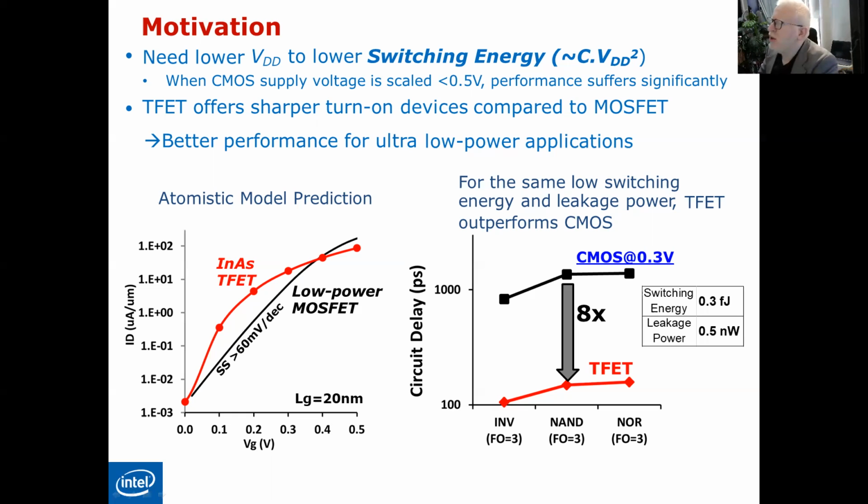So when I told you, for example, that in the past we were using a 60 micrometer technology, this 60 micrometer technology is simply the channel length. This was something like 10, 15 years ago. Now we are using up to 7 nanometer technology. What I mean by 7 nanometer technology is that the channel length of our MOSFET is 7 nanometer.